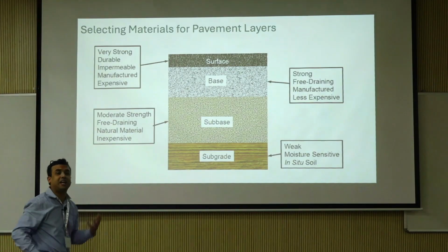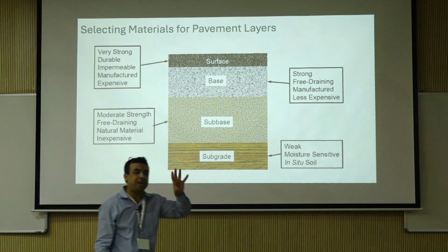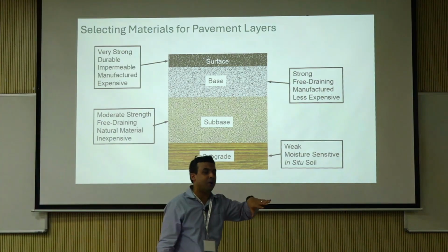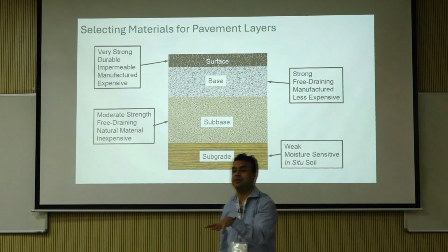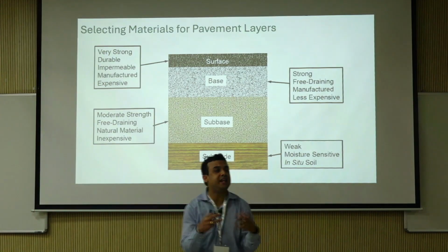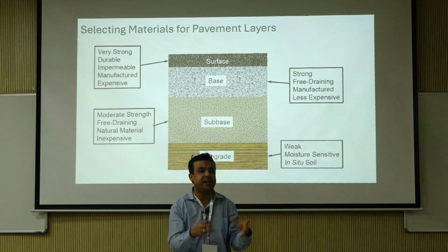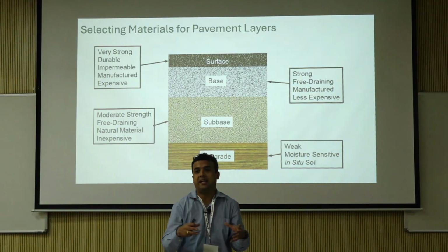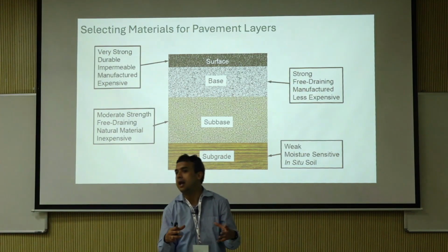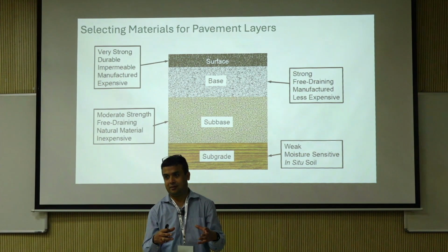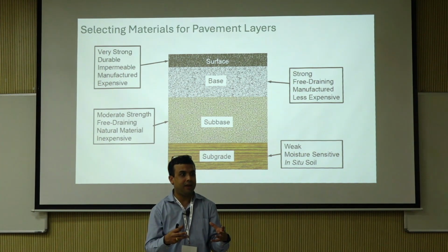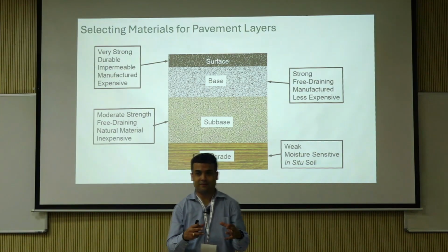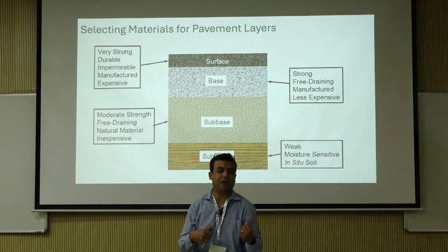Then comes the question again in day 3. These are all open ended. I mean, today is all about introduction anyway. The point is, when you do a resilient modulus testing on an aggregate layer, should you be worried about a drained condition or an undrained condition? Why? Right answer, but why? It should not accumulate water.